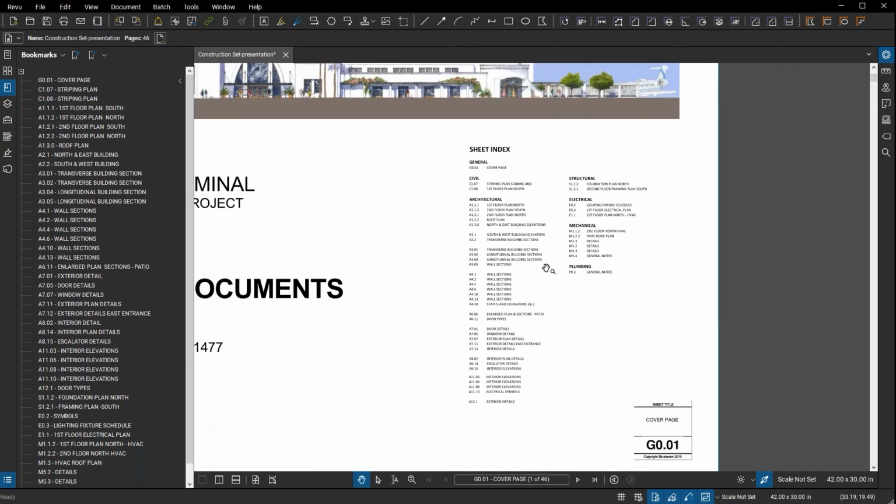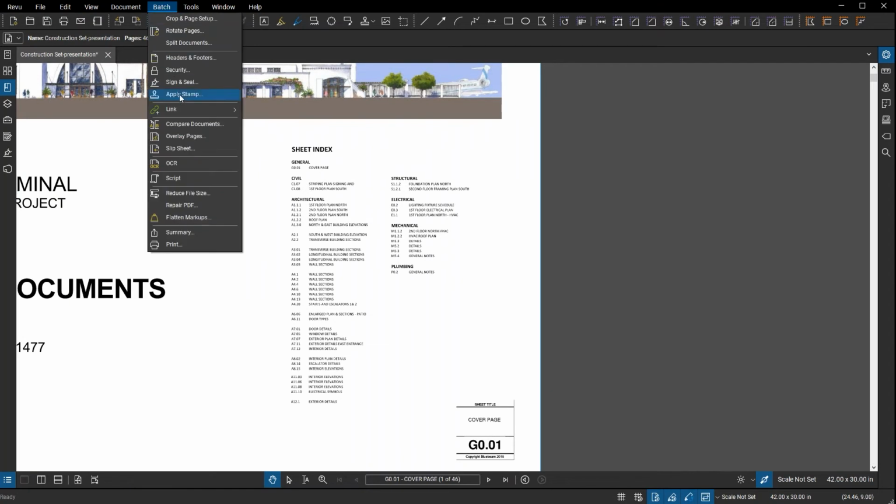What also can be helpful in this process is to create a way to link all these sheets to each other. Meaning that any place where a sheet number is discovered, it links back to the appropriate sheet. So if it's part of a section or a detail, if a sheet number is referenced instead of a note, for example, how do I find a way to link those pages to each other? We can generate that with what's called a batch link. Now this is unique to Bluebeam Revu Extreme, so you will want to have the Extreme version to be able to do this. Not everyone has to have Extreme to take advantage of these links after they have been created. You just have to have the Extreme version to make the link.